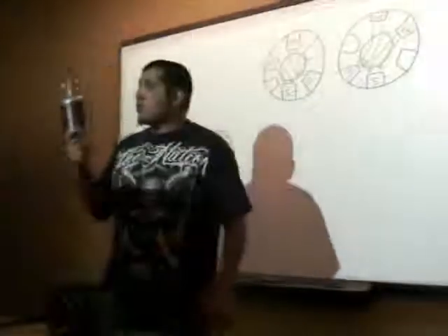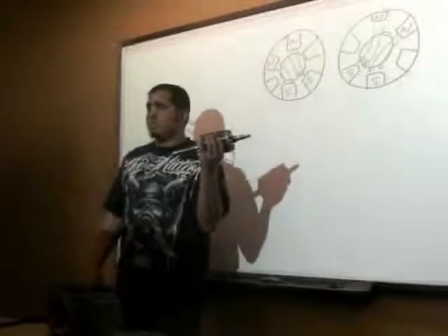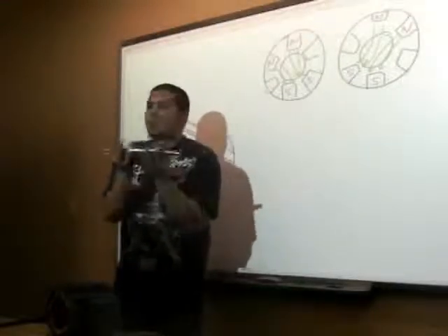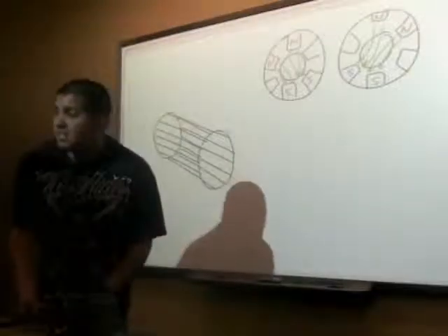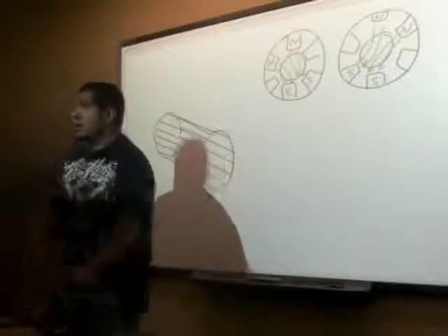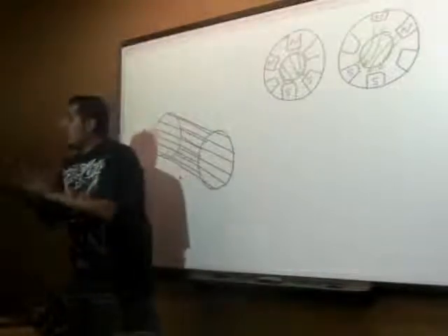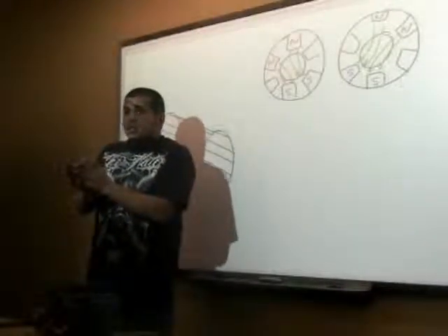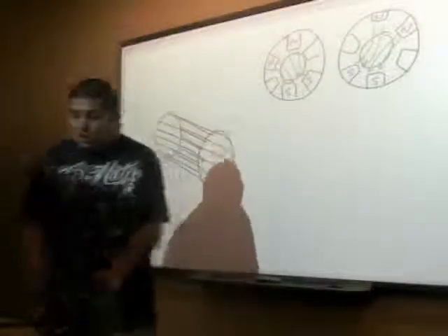Take a look at this thing. We have no electrical connection to this rotor. There's nothing. It's held in here by bearings. There's no electrical connection. It's all induction. What does that remind you of? A transformer, right? Your primary and your secondary have no electrical connection. There's just an induced voltage, right? That's what we got going on here.